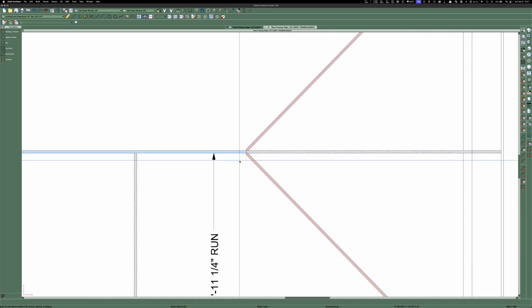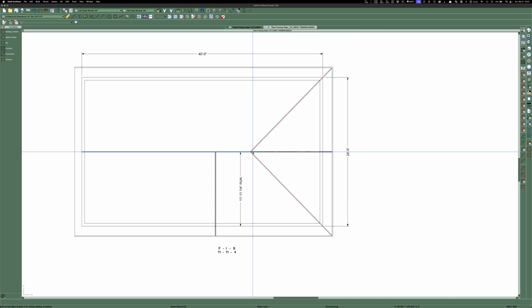So this would be where you're going to want to have, I don't know what's below this house right here, but you're going to want to be able to put some vertical bracing in down, not just onto a couple joists. You're going to want to have it onto a wall. And there's not a lot of roof load. There's some. But it's not like people that panic and they go, "Oh, but you got to point load that all the way to like a footing in the ground."